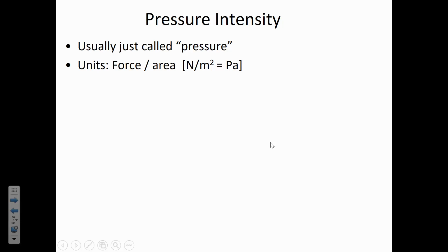But for now, the effect that you need to keep in mind is just that if the surrounding pressure falls below the vapor pressure of the liquid, then those little bubbles will start to form. It's essentially that boiling occurs inside of the pipe. And boiling inside of the pipe is bad because those little vapor bubbles, they're tiny, but later on they'll collapse when they get into a higher pressure zone. And as they collapse, it occurs very rapidly, and it sends that high energy shock wave, and it will cause damage to the pipe or to impellers of pumps and turbines.